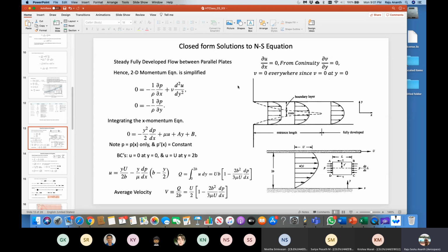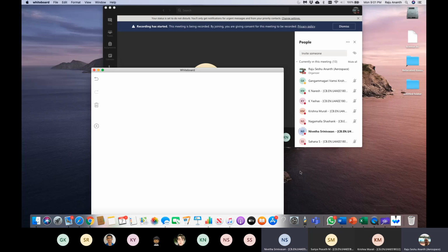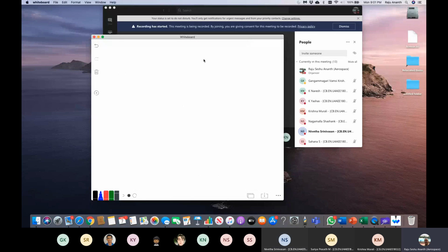Okay, so let me just explain that. That's a good point. It's an important point. So what are we trying to do? We want to get the Nusselt number, which is h times some characteristic length lambda divided by k. Now the heat transfer is k dT/dy at y equals 0, for unit area, of course.